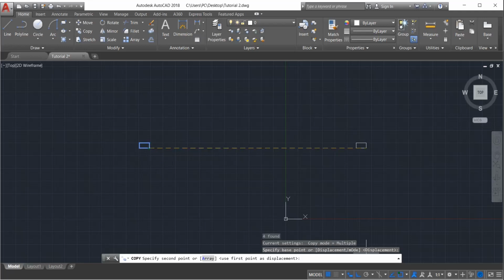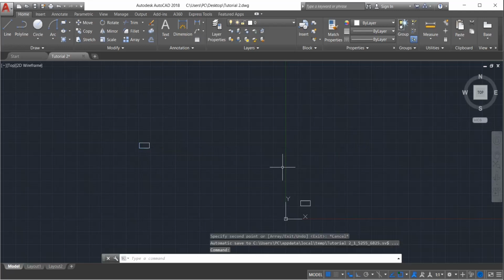Just look at this. If I say I want to bring this corner, please put it. Okay, now ortho mode is on. It will restrict me to only move either vertical or horizontal. So I turn it off so that I can move freely. So I say, please bring this corner and put it like here. Even you can make more copies, but that is what the base point is. Then I can delete this.